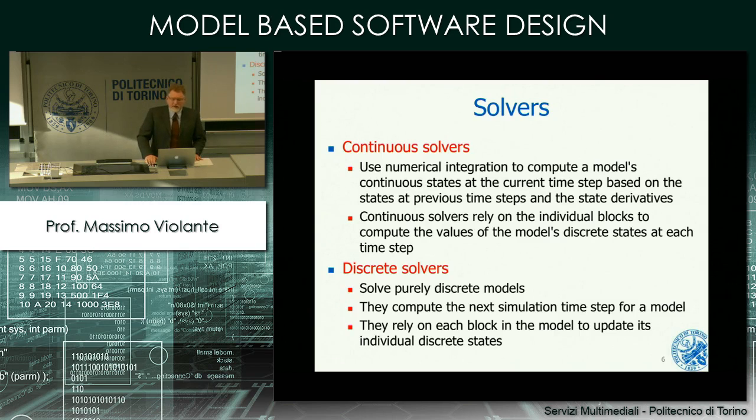The other element that you can tune when defining the solver that you want to use is the way in which Simulink has to deal with time. You can have a continuous time solver. This means that delta, whatever it is, is divided in multiple sub-instances of time.